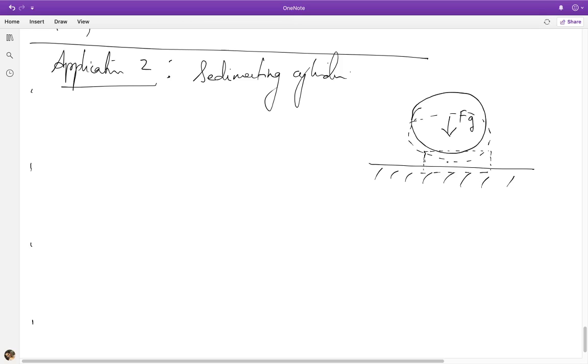So based on our understanding so far, we expect that when the cylinder almost comes in contact with the wall, large pressures would be developed in the thin liquid gap region, right? Because you have to force out fluid from an increasingly narrow region where the viscous stresses that counteract that motion keep growing. So the pressures that you have to develop also keep rising, and that pressure counteracts the falling cylinder and slows down the rate of its sedimentation.